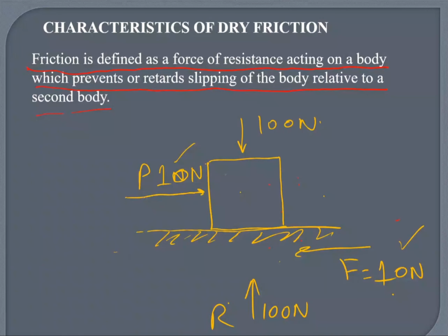If I have this box on a concrete ground, rough ground, I increase the force slowly from 1 to 100 Newton. I'm increasing the force P. At some moment, assuming around 55 Newton, the object will start moving. Okay? So I've got a maximum friction force of 55.